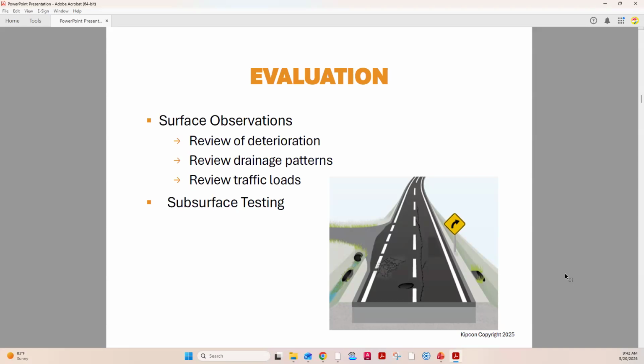And the reason I do that is because even though I am looking for areas of deterioration and areas where there may be drainage problems, I cannot always visually determine where there is a drainage problem. So for people who are familiar with the community and live in the community, that's the time when you first begin the project to make your engineer aware of what your specific concerns are and not wait for them to find them, because it's not always visually apparent.